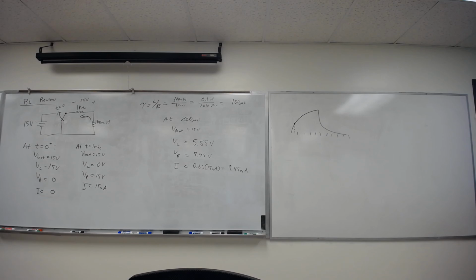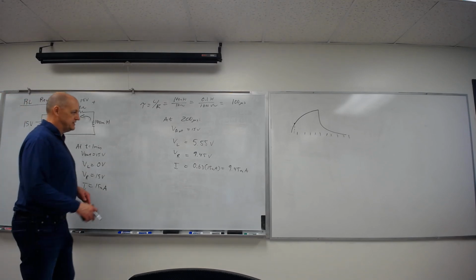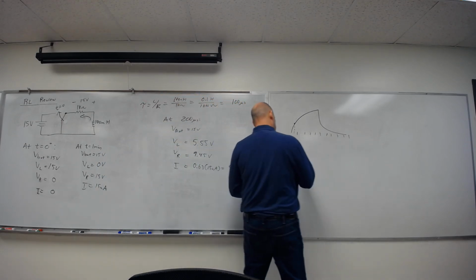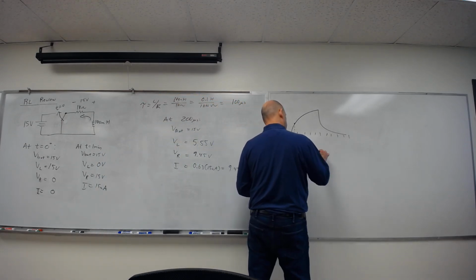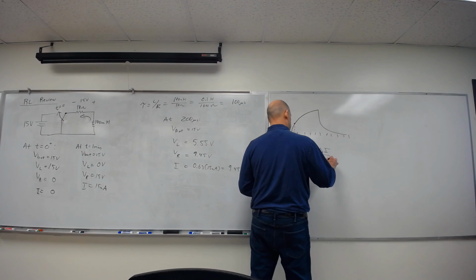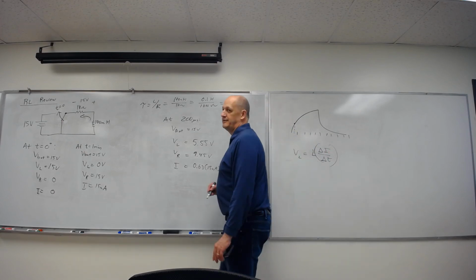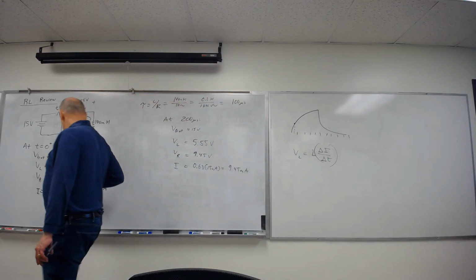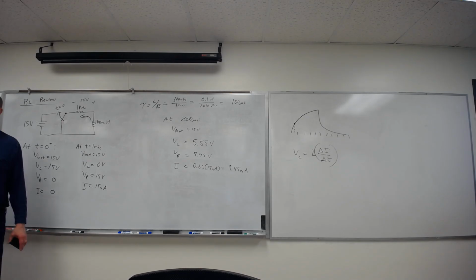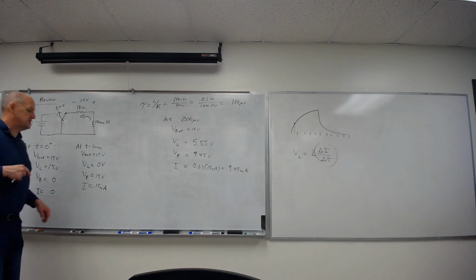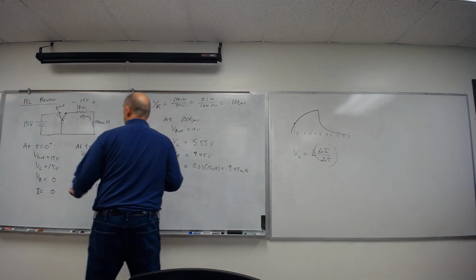Good with all this? My inductors work the same as it calculates the time constant. Well, I should say work the same. You have to pay attention to this detail. If you recall, the voltage on the inductor is the inductance times how fast the current's changing. So when the current's no longer changing, there's no voltage. When the current's changing rapidly, there is voltage. Okay, let's try discharging real quick, and then I'll let you go.